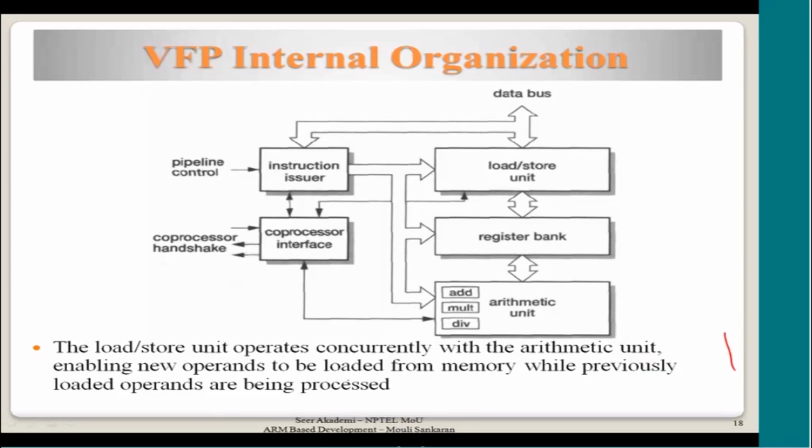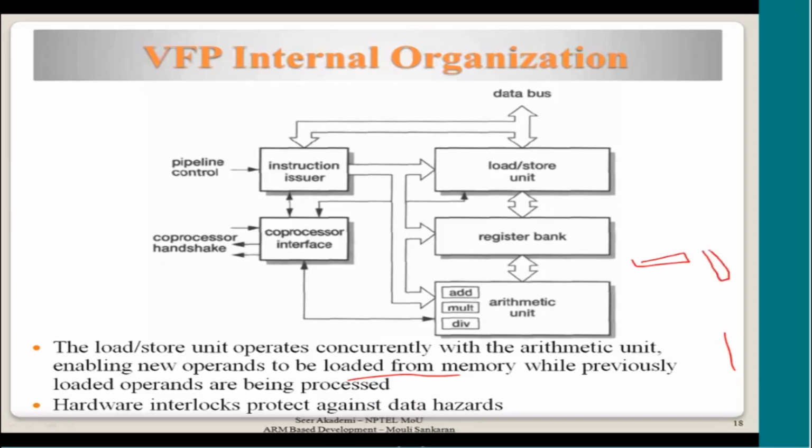The arithmetic units can work on the previously loaded operands. Hardware interlocks protect against data hazards. I told you that between two vectors there can be a data hazard, but not within the vector, right? So there are some hardware interlocks.